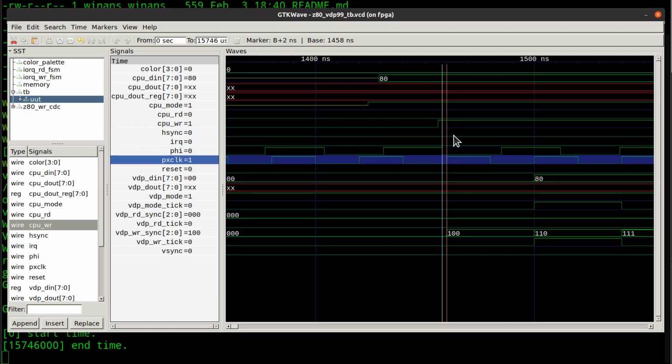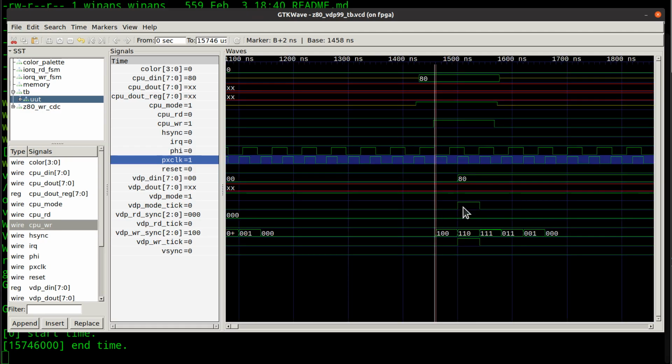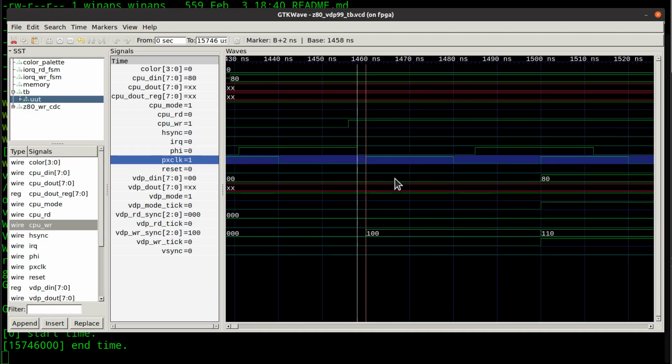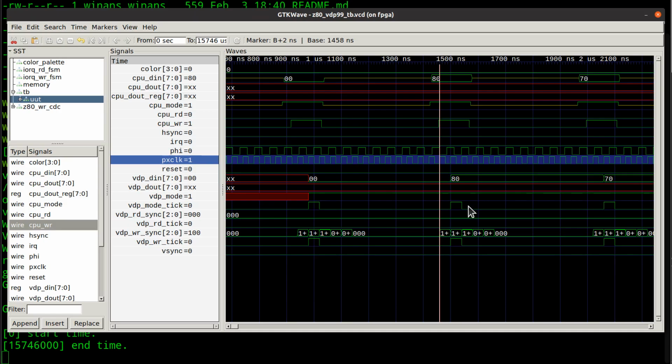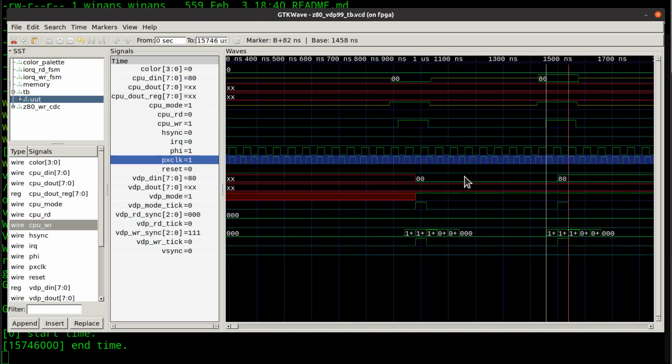Now, in the simulation, what is it doing here? It did see that it's a 1, which is what's shifting in down here, and we'll take a closer look at why that is in a little bit. Okay, but the simulation has an infinitesimally small setup and hold time. 2 nanos may not be good enough. Now let's look at the other edge over here.